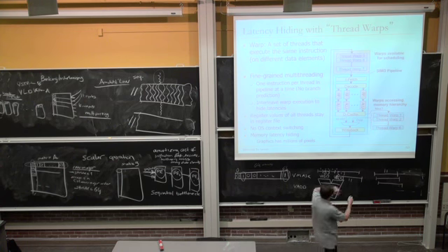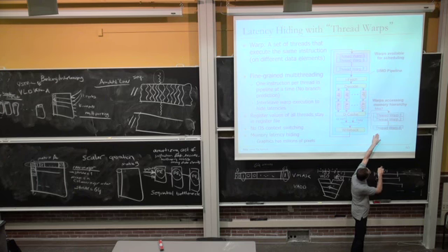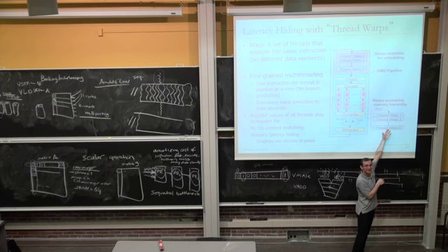So think about this. Let's say you're doing a load instruction. You're doing the same load instruction in the same thread warp, and only one of them missed the cache. You don't really need to stall that one of them. What you could do is add additional bookkeeping that removes this thread, puts it in a different warp, and places some other thread that is executing the same instruction into this warp.